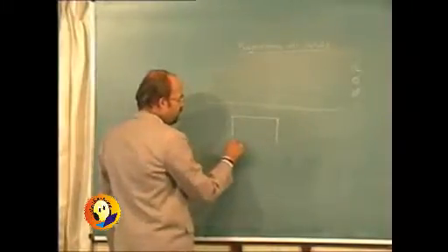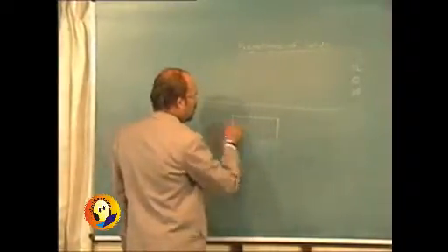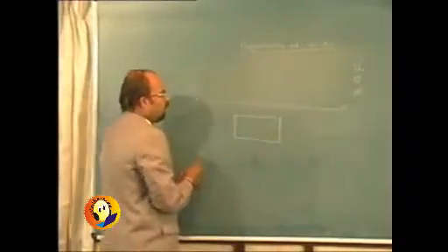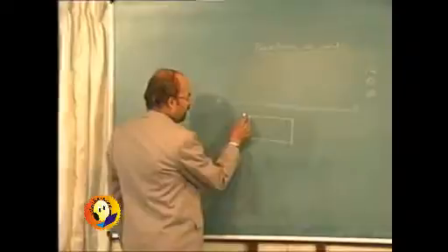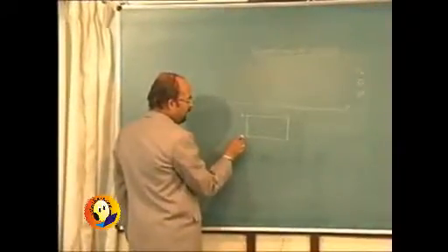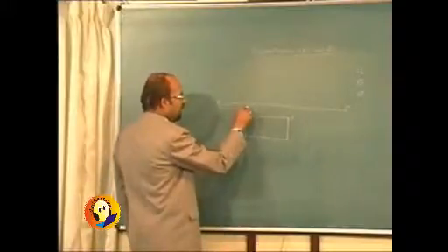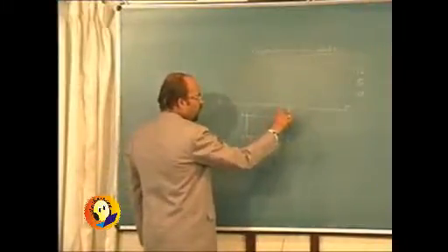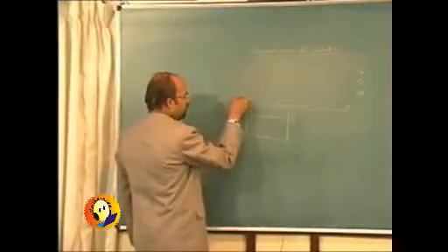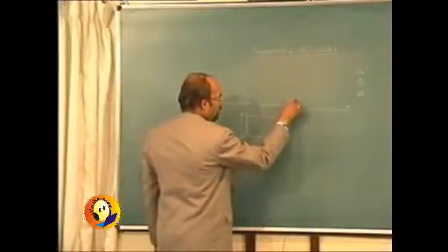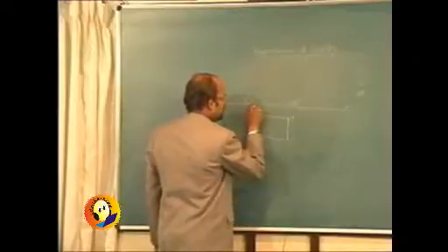which is kept on the horizontal plane, then the 4 points of the rectangle, which are namely A, B, C, D, they will have their elevations on XY line, giving us projections of plane in its elevation form as a straight line which is on XY.